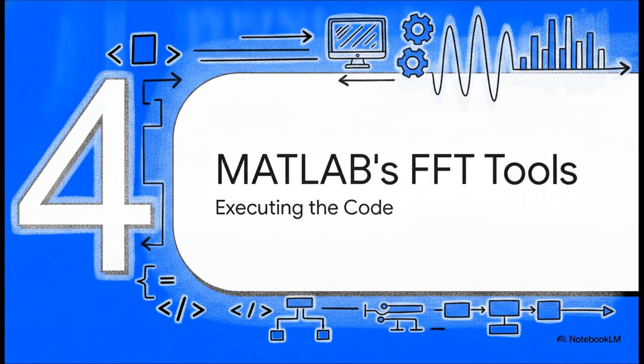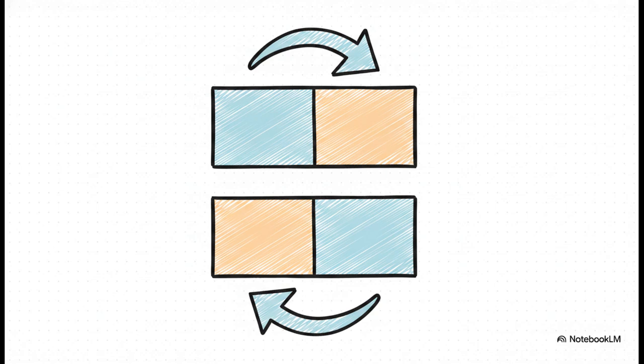Section 4, Navigating Matlab's FFT Tools. Okay, so now that we understand the theory and the corrections required, it's time to look at how to actually code this solution properly. If you're working in Matlab, there is a very distinct difference between the FFT command and the FFT shift command. If you just run a standard FFT, the plot is going to output a mirrored reflection in its second half, so the positive frequencies come first, followed by the negative frequencies. It's mathematically accurate to the algorithm, sure, but it is super hard for a human to read.